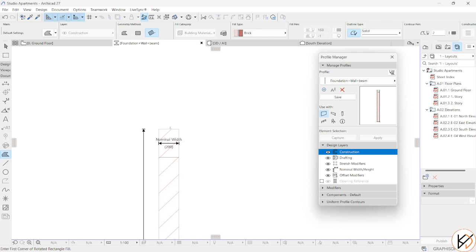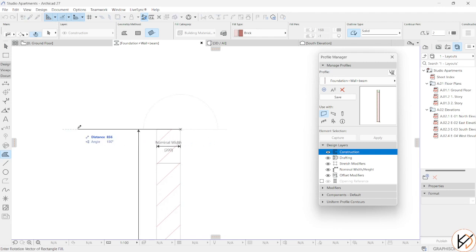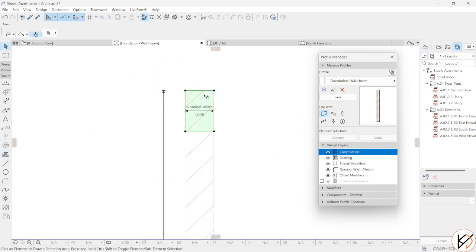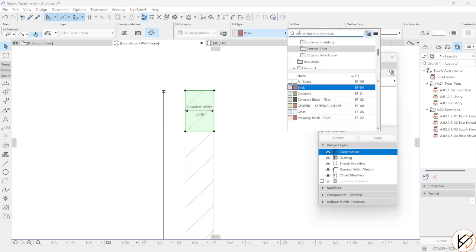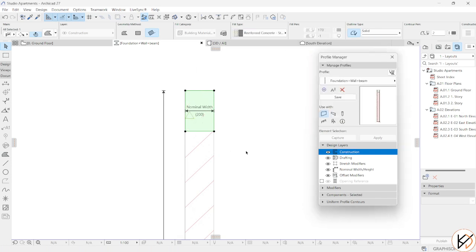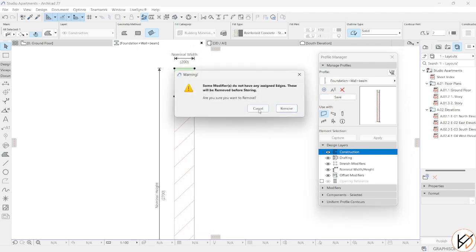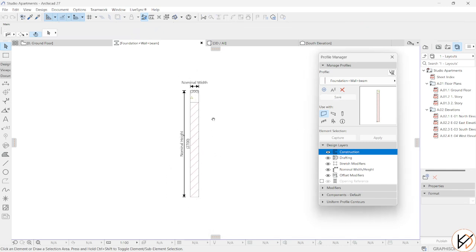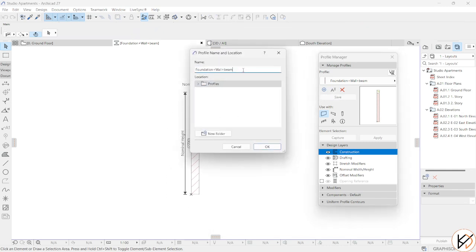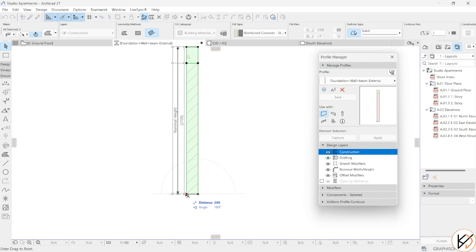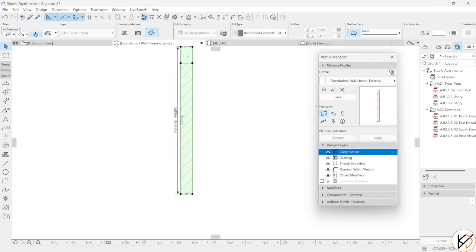And then we take this, we draw another on top, 300. So this is 2.7, but then the beam also has the slab. Remember, in practice the slab is right around there. So we'll leave our beam where it is right now without extending it. Change the material to reinforced structural concrete, and hit save, and say remove, and say okay. So we're going to rename this and say external. And because I just like using center lines when I'm working, it's so much simpler and faster, I say 100 and say save.